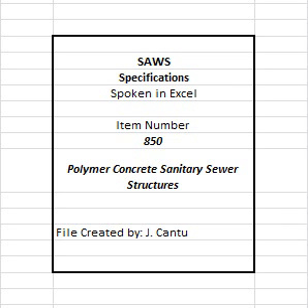16. Cones, reducer slabs, base slabs, and adjusting rings shall be of the same material as adjoining riser sections. 17. Structures shall be designed to withstand all live loads and dead loads as described in project plans and specifications. A. Dead loads shall include overburden load, soil side pressure and hydrostatic loading conditions. B. Structure wall thickness shall be designed to resist hydrostatic pressures with a minimum safety factor of 2.0 for full depth conditions from grade to invert.